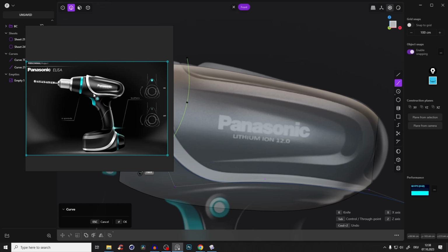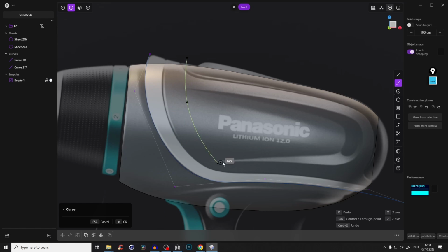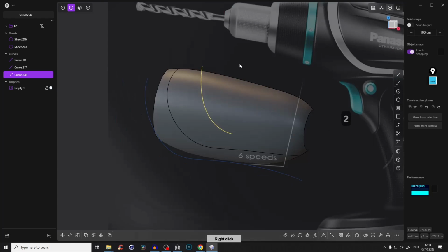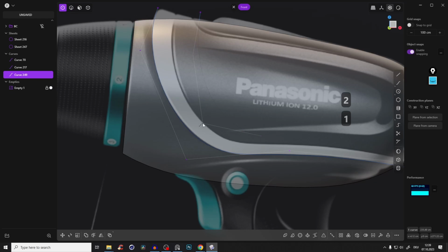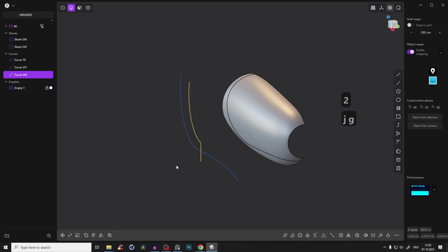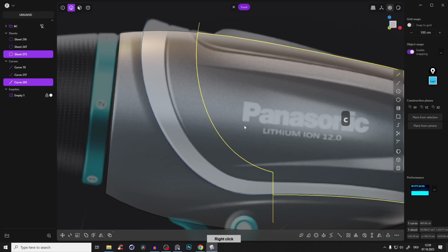Also, you see here we see some shadows, so it starts somewhere here to go outwards, to somewhere like here. And let's maybe adjust those points. And again, you see it's in the middle. I really don't like this. But anyway, something like that, and create a line and just go here downwards, and select both lines, press J to join them, and G to bring them here to the front. And also again, press C and cut our surface.